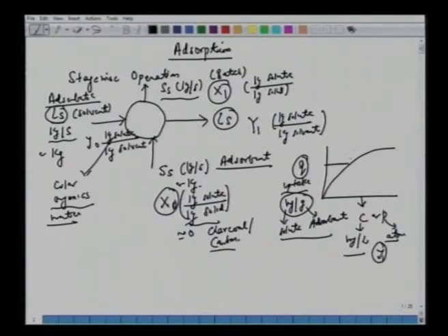So given fixed T, you have these isotherms available. For much of C, you have Q. So instead of working on this C and Q, in this problem let's say we are working on x and y. These are all solid-free bases. You know the advantage we have said earlier also: the operating line based on the solid-free mole fractions remains linear, remains constant. So that's the advantage of working on this. So let's come back to this.